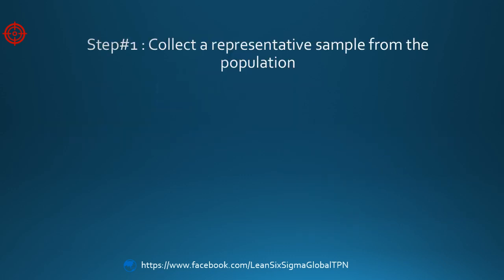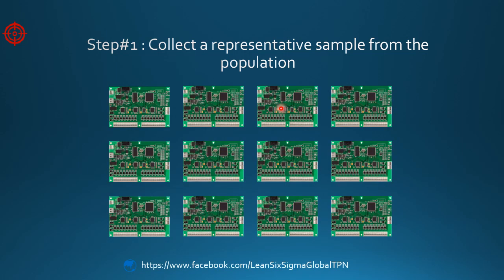So now let's perform a Gage R&R study to investigate these two types of precision in the PCBI viewer measurement tool. The first step in the analysis is to take a representative sample of paths to measure. For the circuit board components, we choose 12 boards with distances that range from 4.94 to 5.05 mm, which represents the typical range of distances between components.